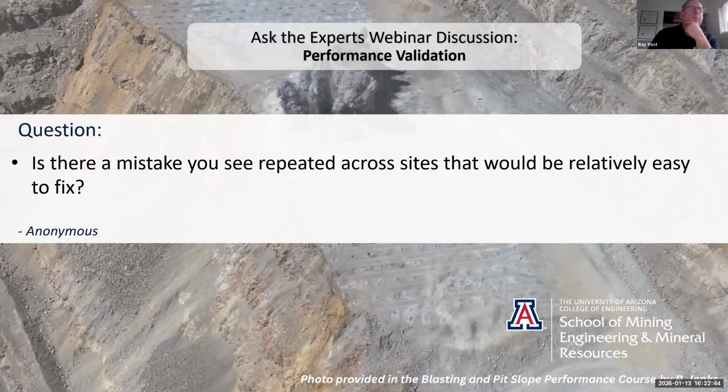And on that too, in terms of the ease, it's getting easier and easier to have somebody that can operate a drone and provide pretty detailed scans of your post-blast walls. This stuff that's available now is just fantastic, and being able to collect surface data and plot it practically in real time. It's not difficult to have a survey of the bench same day that the bench is done being excavated. So that part is pretty easy.